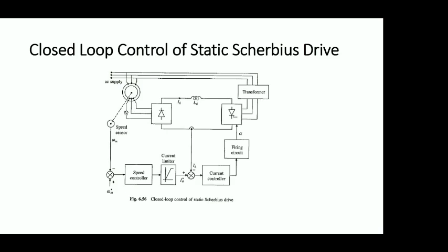There are many types of tachos: digital tachos, which count the rotations, or analog tachos, which, if you connect directly to your rotating part, act as a DC generator and generate some voltage. That voltage is taken as the omega m signal. So that is the speed sensor.